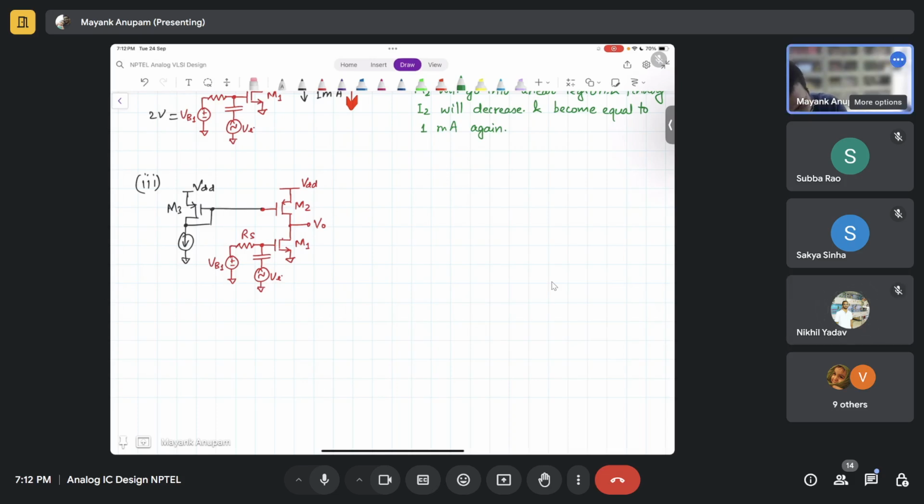Exactly. Very good. So this guy here has a constant current of I naught, right? And this will always keep giving I naught current output, isn't it? However, M1, because of some change in its threshold voltage and all, can maybe demand more or less current, right? That can happen, isn't it? So this is again not a very good way.